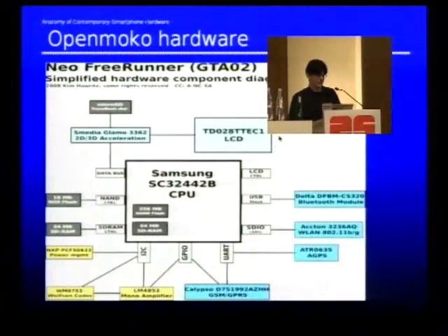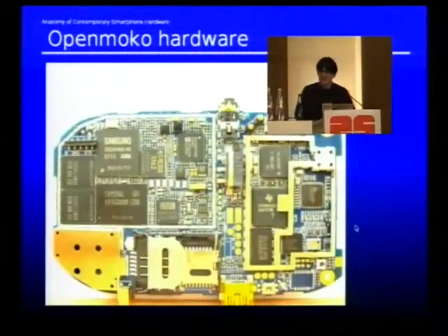This is the LCD display. And that one, again, has an SDIO interface, which connects to the SD slot, because, well, the SDIO controller here is used for the Wi-Fi interface. So you see the kind of problems. Your hardware interfaces are limited in number. You add more and more peripherals. So, where do I move it? Do I shift it here, but then I lose this? Where can I connect there? Where can I connect that? No. Okay, that's the overview diagram.